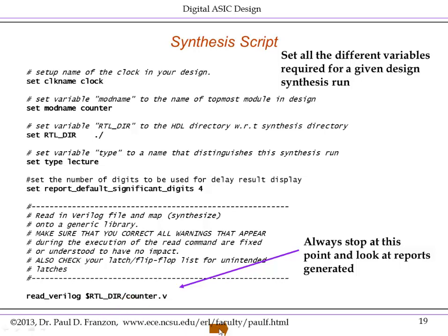It will give you warnings if there are problems and errors. We'll talk about some examples of these warnings in the next set of notes. If you get these warnings, you have to fix them. You do not have a synthesizable design if these HDL warnings are actually there.